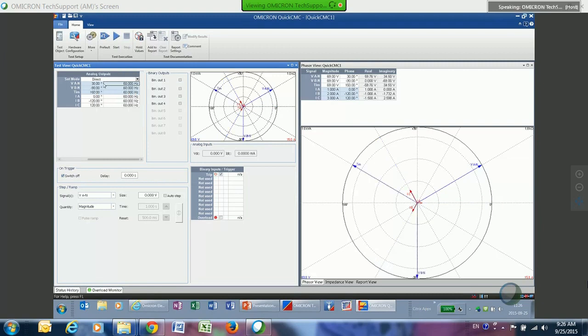Likewise, you can do the same here with your phase. So I can select this at 0, but let's just say, for instance, I wanted to make this 30 degrees. If I change that to 30 degrees, right-click on it, I can actually balance my angles. So now it balances everything based upon the 30 degrees that I put there in phase A. And if I come back and select 0 and rebalance them all, whoops. And now basically that's just like what you would see in a normal system out there.